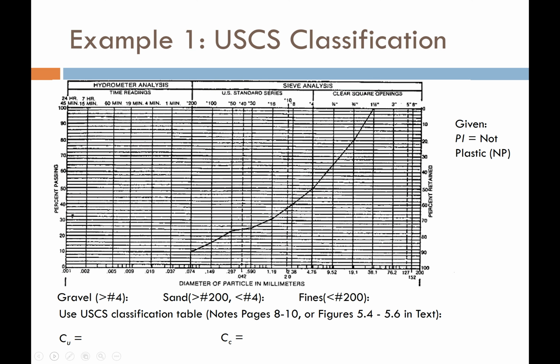Okay, so let's go ahead and work our way through a Unified Soil Classification example. There's a couple of things that are given. One is, here's our gradation curve. It may look backwards from what you guys have seen on our earlier slides. That's because we're increasing particle size moving to the left instead of to the right.